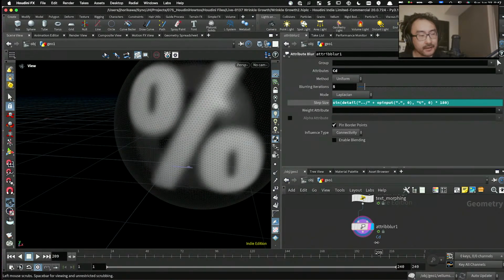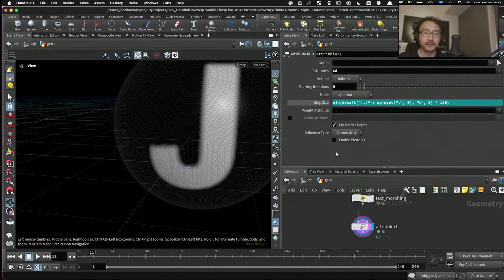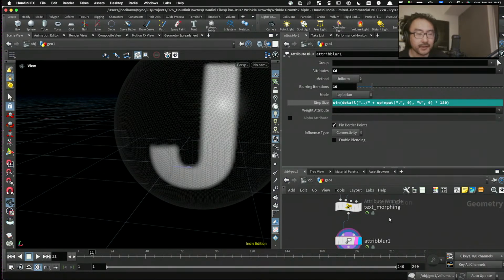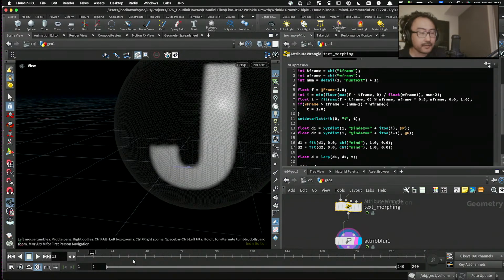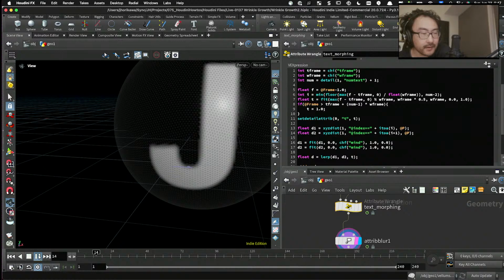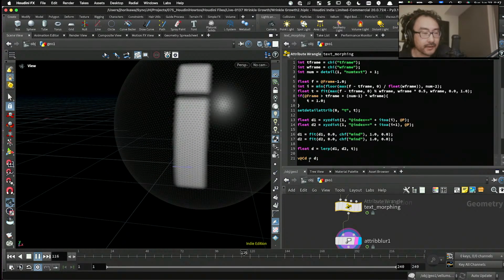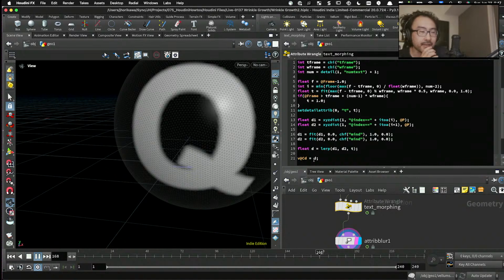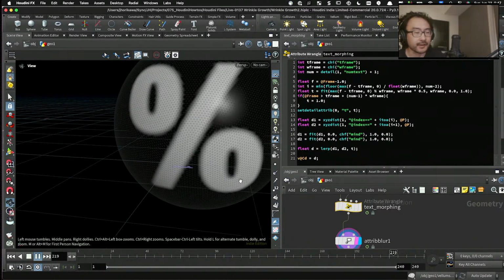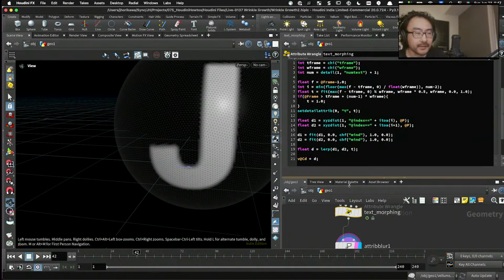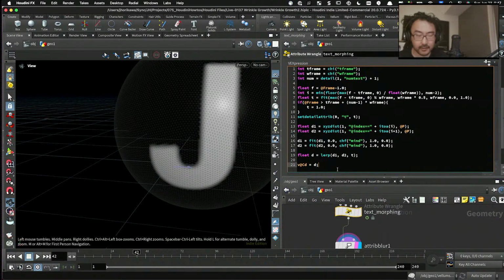Okay, seems to do well. I'll make this back 10. Okay, now that I have this mapping, currently it's being applied to colors, but if I just change this to a mask, then I can just use it as it is for the later Vellum setup, I think. So let's do that.